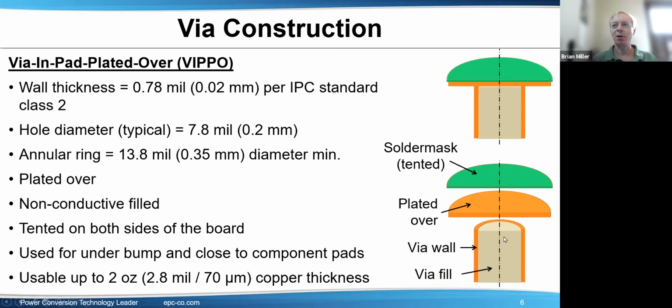One, there's a stable fill that stays put, doesn't come in or out, and a nice flat surface, and that flat surface is protected, and no solder comes down. But exactly the different situations of having the solder mask tented, that's probably another good question, unfortunately, to ask of some of our thermal experts. Okay. Just make a note. Because I can see a partial tenting might be good enough in some of these cases.